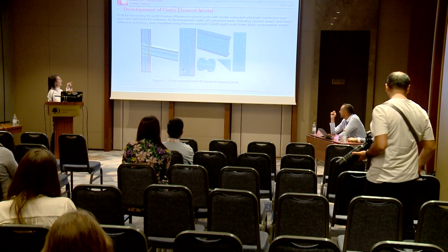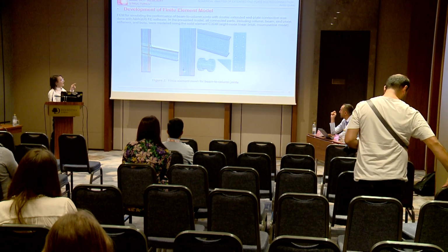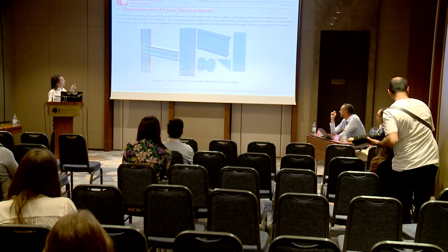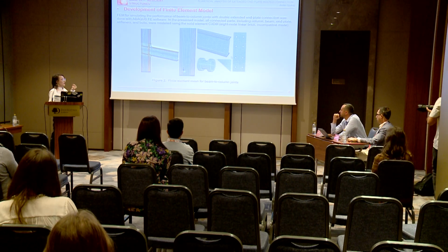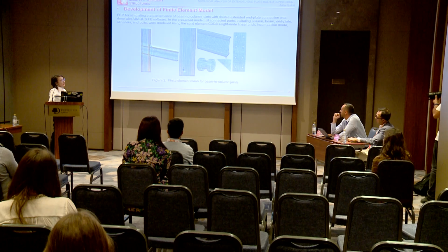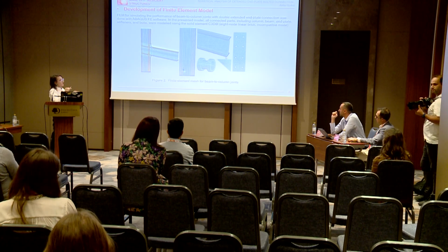But in this near zone, for example at the bolts, end plate, and stiffeners, the mesh size was smaller than here, because here the concentration of strain and stress is larger, and I needed to separate it.